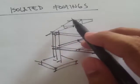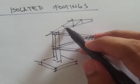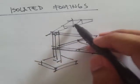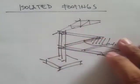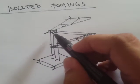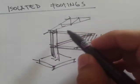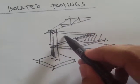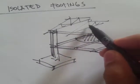So live load, dead load, and once they're transferred into trusses, the truss will transfer the loads to the attaching member. In this case, the truss is attached to a column, but you can also design a truss that's supported by beams.